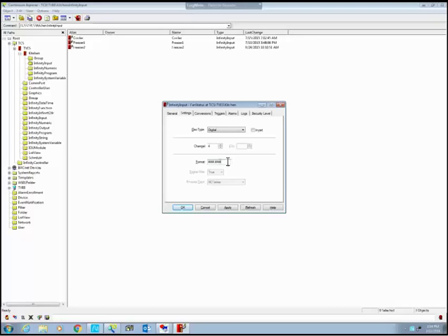The formatting for a digital point is a dollar sign and some pound signs. So that's going to show you on or off. You can have it if you want 0 or 1. You can have just the number signs. That would show you on or off for 0 or 1. But because we want a fan status, it's going to be typically an on or off sign. Okay.